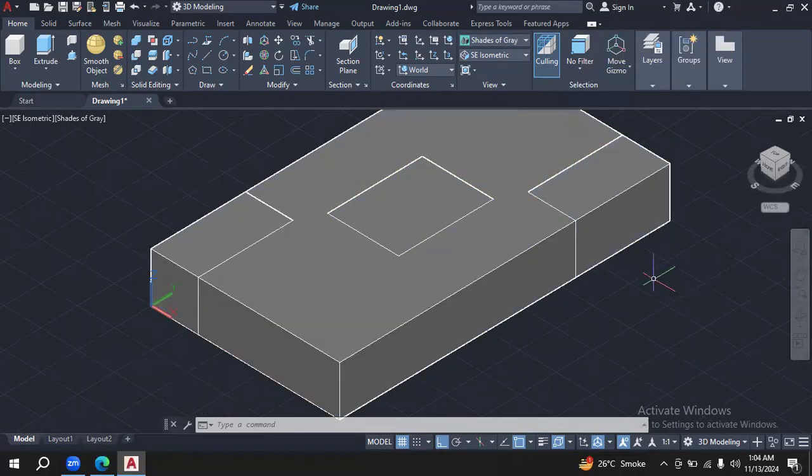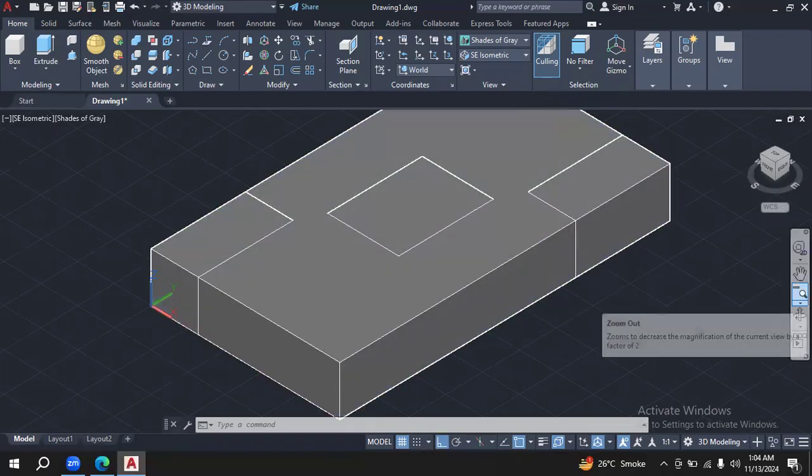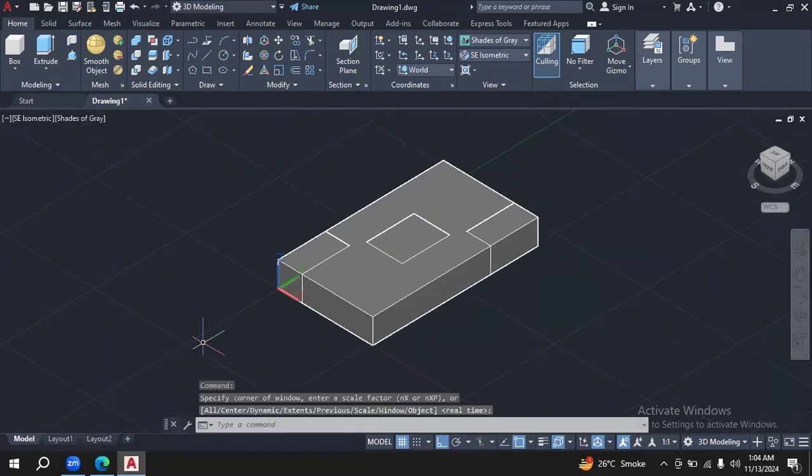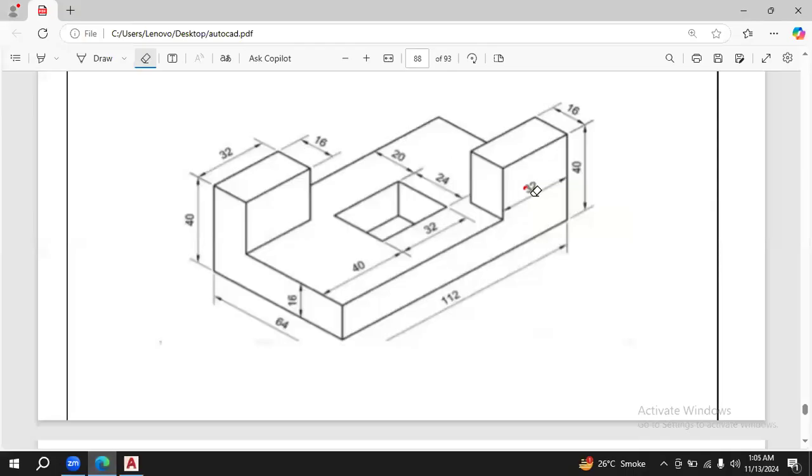Why I prefer to do it this way is that we have to pull this middle rectangular block to create a void space. And we need to pull out these corner rectangular blocks to show the extrusion at the corner ends. So therefore, it is better to apply the extrusion command in the very first step on all of the blocks. Once we have this case, the next step is to apply extrusion over these two blocks and the press and pull command on the middle section.